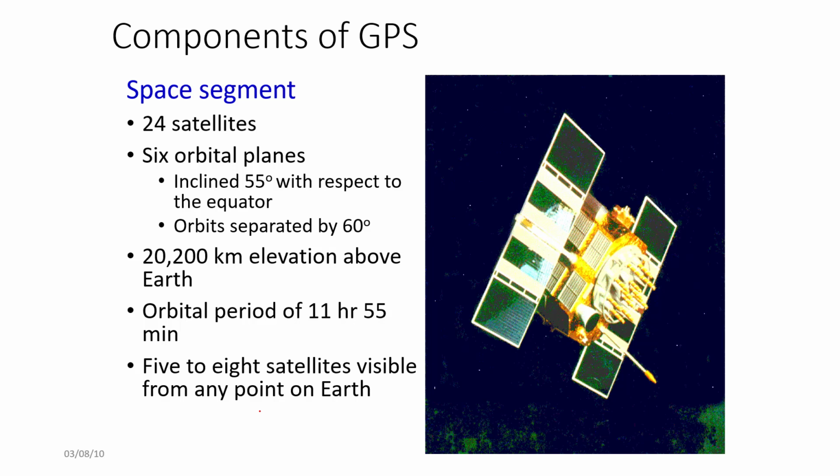One reason is that we don't want satellites traversing too fast. Otherwise, we'll quickly lose signals. So that is the reason this was considered relatively safe. Also, we would not like to place the satellites in a geosynchronous orbit of 36,000 kilometers, because then the signal will become too weak. So the idea is that at any point of time on Earth, we wish to have 5 to 8 satellites in the range.